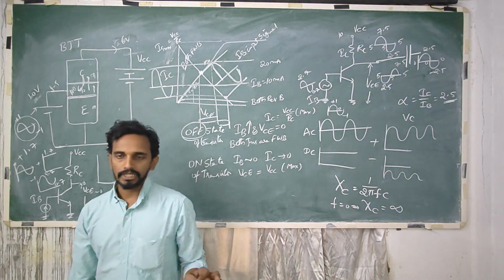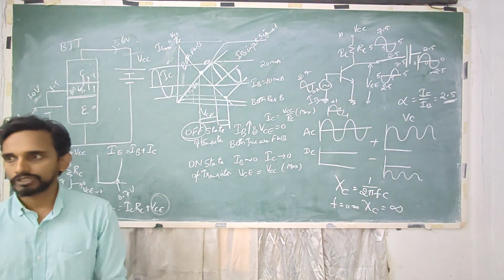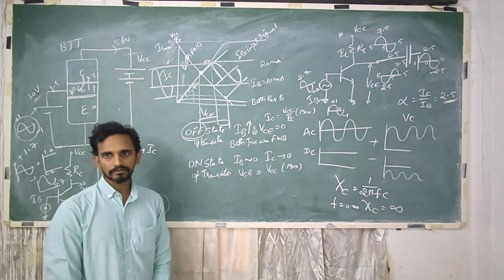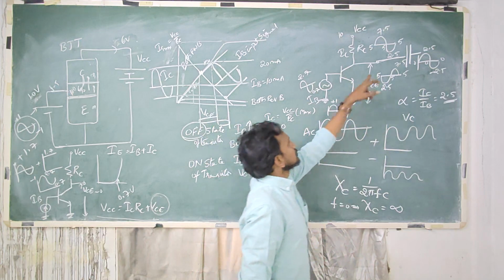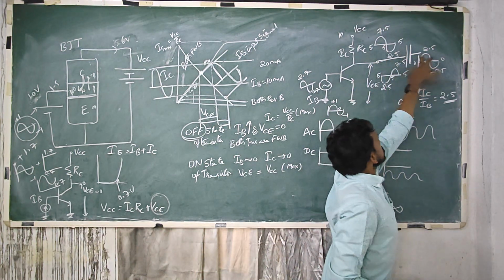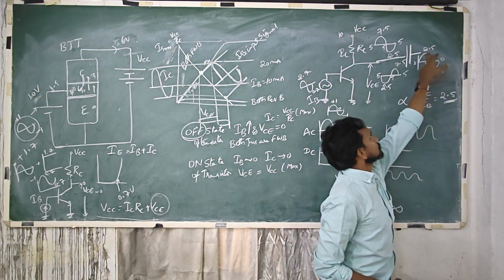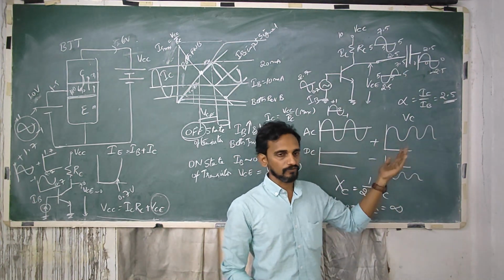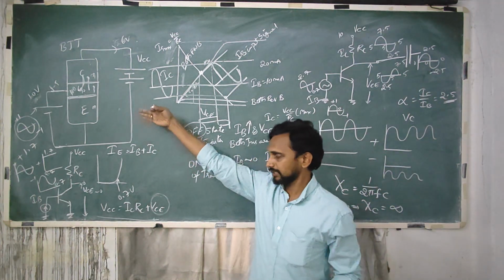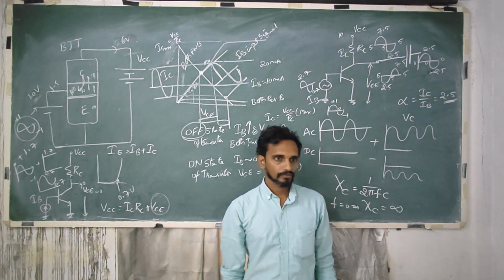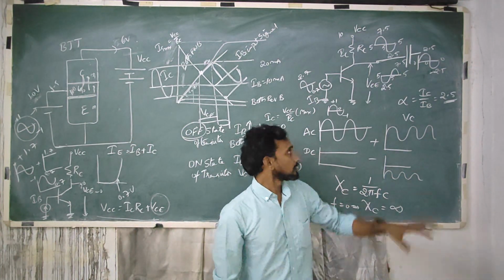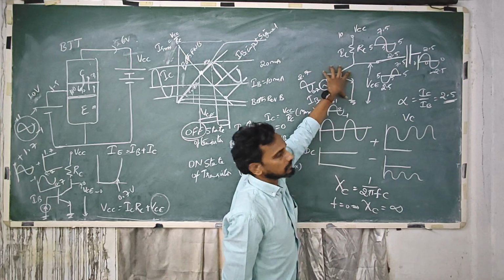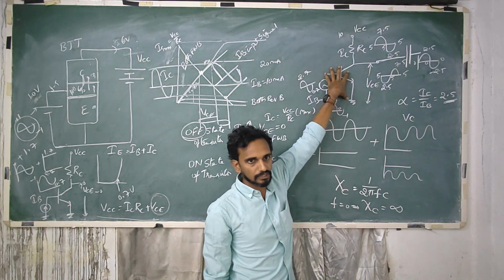So it stops entire DC current and allows only AC current. Okay, so output after this capacitor will be like this, 0, 2.5, minus 2.5. And further, if you need any further amplification, you may need an additional bias. Okay, so that will be taken care by this circuit itself, right?